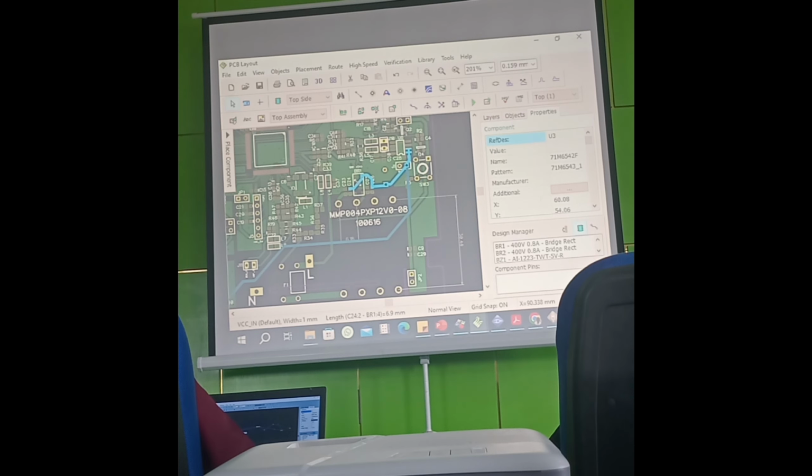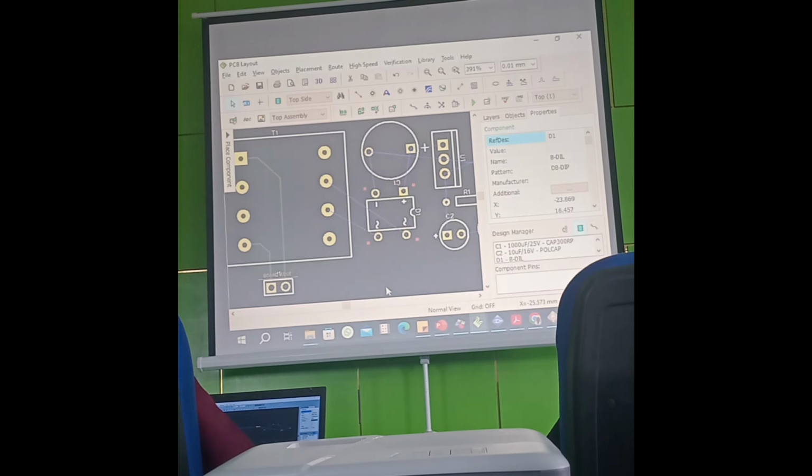But after this bridge rectifier, because the rectifier used here is SMD, surface mount, you can say at that point that's where the AC stops. There's nothing like copper pour for AC. You run the trace alone without any copper pour, and you avoid any DC component around it. So this arrangement, let me just finish it up so you see what I mean. You see?